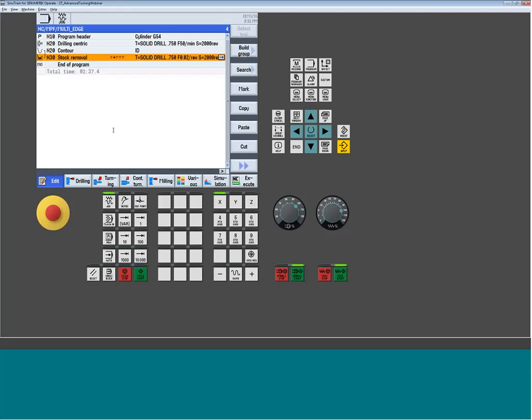You can use this certainly for gang type of tooling scenarios. So let's say you got a turret, but you have one tool configuration that maybe has a couple different heads on it, like a turning tool and a threading tool, all built on a modular block. You can buy those. That would be an easy way to jump between those little stations. And now all of a sudden you took your 8-position turret and gave it an extra 2 tools. So you can start to certainly get very creative with this whole mechanism. Okay.